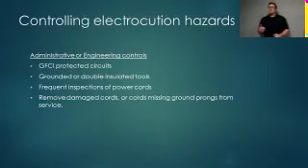A lot of times there are nicks or cuts in the wire on electrical cords or power tools, and those are supposed to be removed or repaired, and oftentimes they're not, which is why there are so many issues. So the biggest hazards are generally with power cords and the cords on tools. Those are where we run into problems most often.